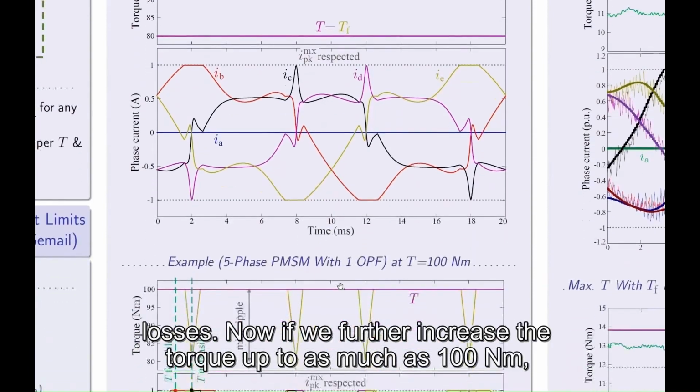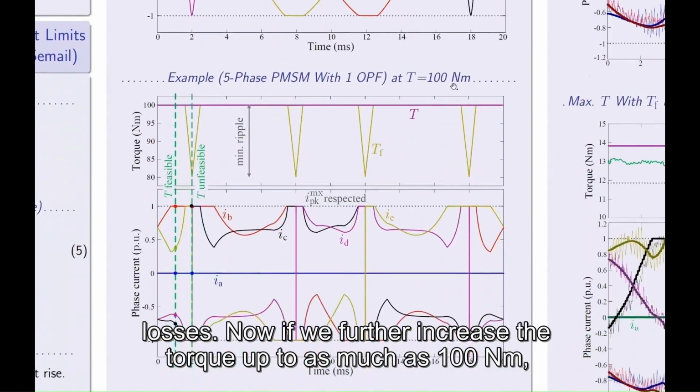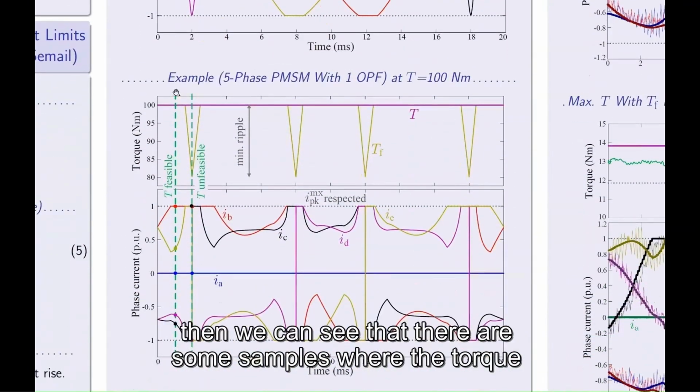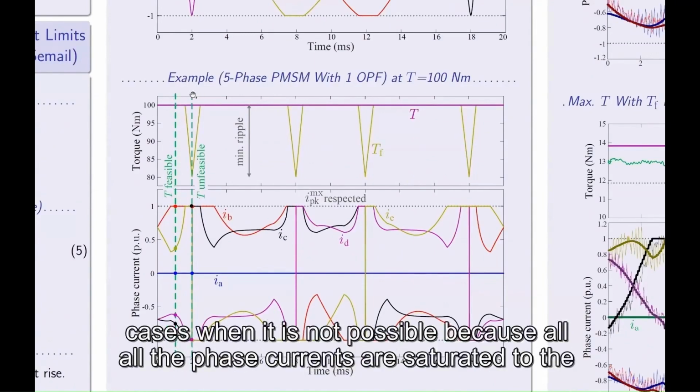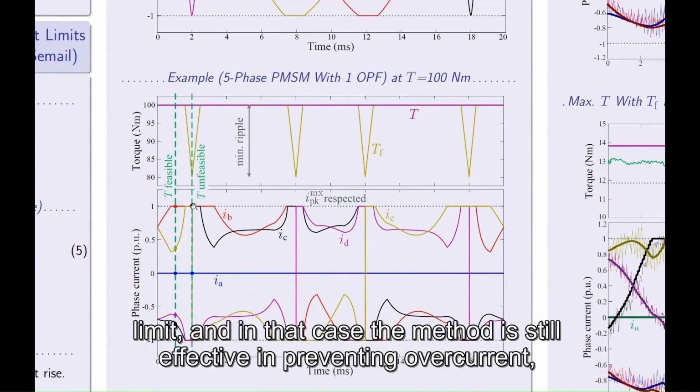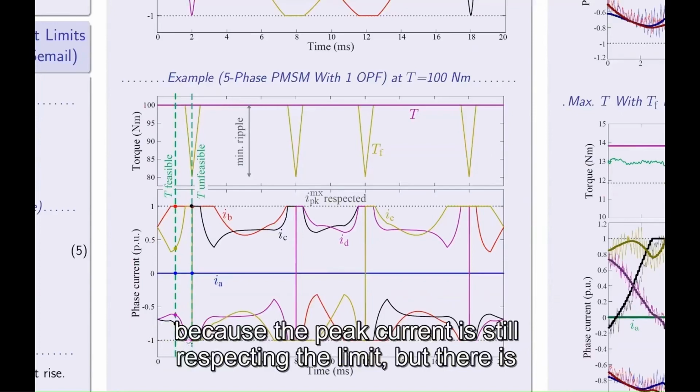And now if we further increase the torque up to as much as 100 Newton meters, then we can see that there are some samples where the torque reference can still be achieved, like this vertical line. And there are some other cases when it is not possible because all the phase currents are saturated to the limit. And in that case, the method is still effective in preventing overcurrent because the current is still respecting the